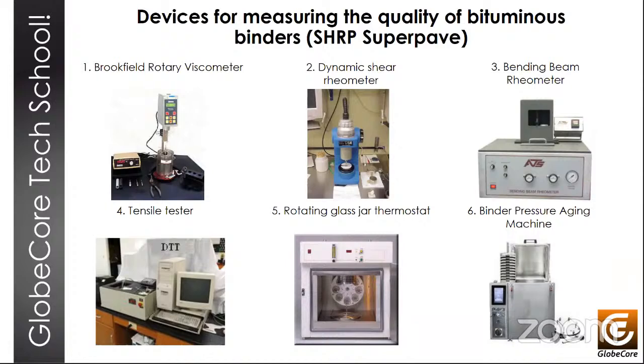And to assess the crack resistance of bitumen binders, several indicators are used. The first is the stiffness modulus at temperatures of 10 degrees centigrade below the minimum asphalt concrete temperature adopted for each specific zone. This stiffness modulus must be equal to or less than 300 MPa. It's determined using a special device called a beam rheometer, which makes it possible to measure the deflection of a bitumen beam pivotally supported on 2 supports with a load placed in the middle of that span. And this device is called a bending beam rheometer. In the road surface at low temperatures, bituminous binders are subjected to stretching.